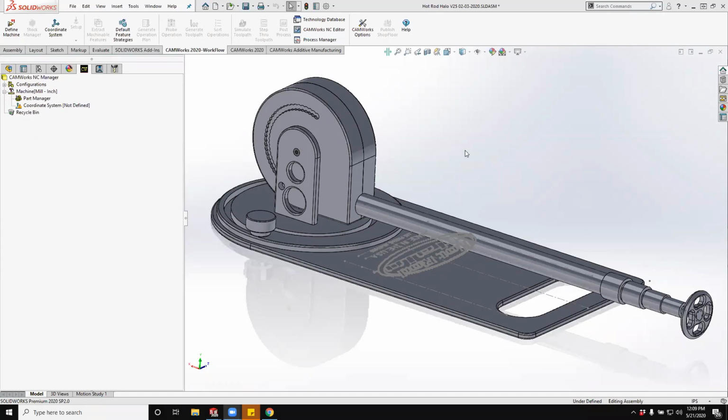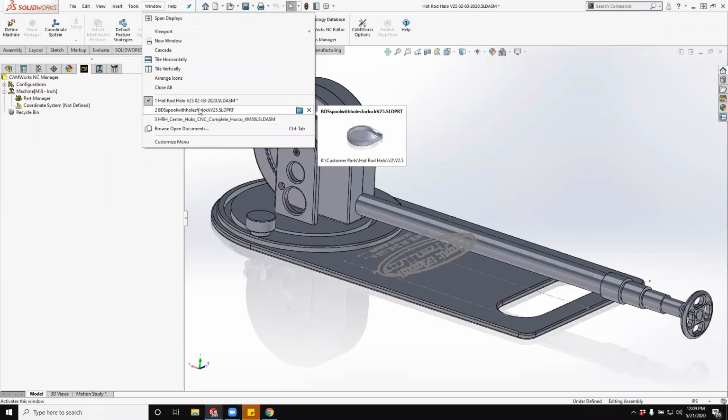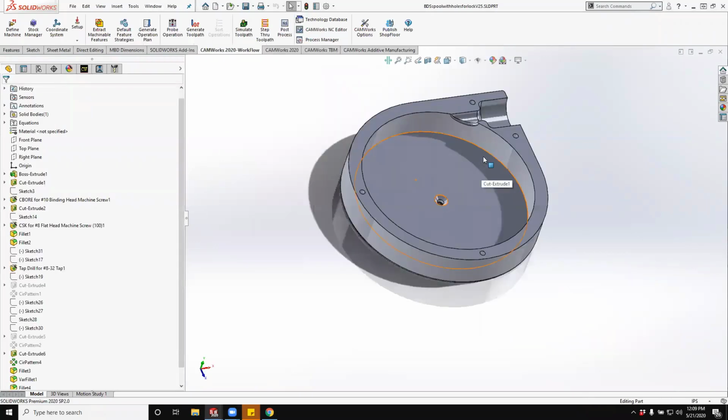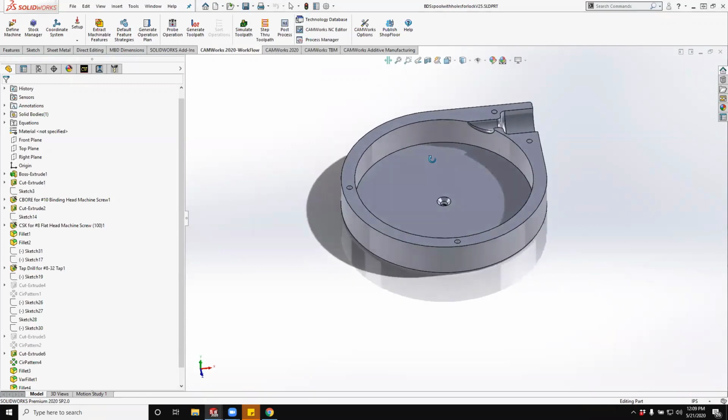So anyway, let's look at how we would machine that, and let's look at the capabilities of SOLIDWORKS CAM Standard. If we wanted to work on this part, we could go ahead and open that part up. And we'd immediately have 2 choices. We could save the CAM data right with our original CAD model, or we could choose to insert this part into another part, and then we could have a very specific manufacturing model.